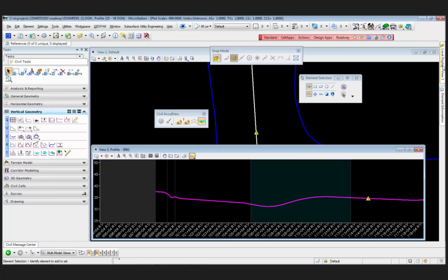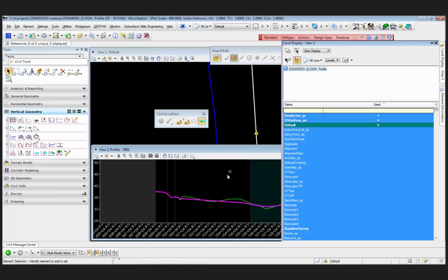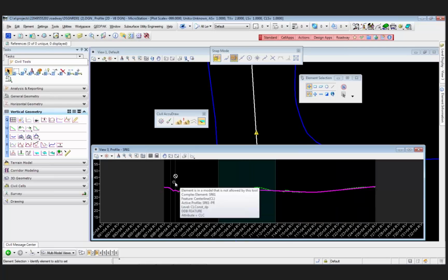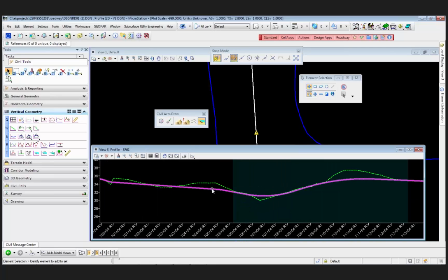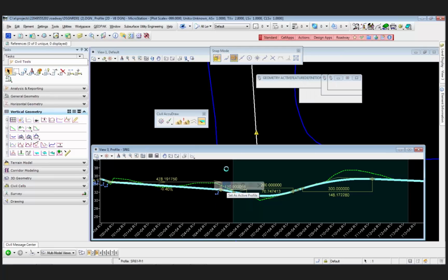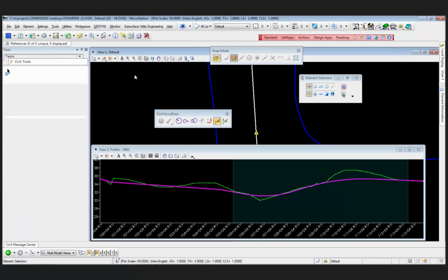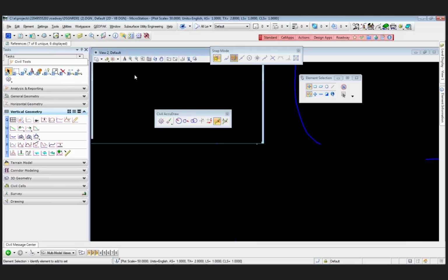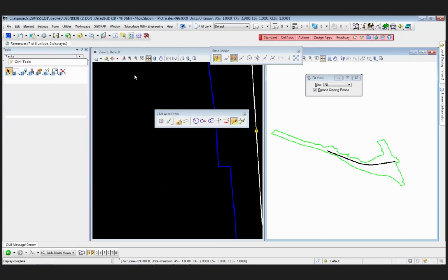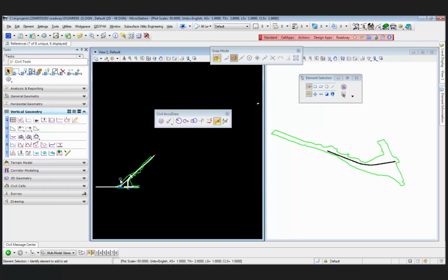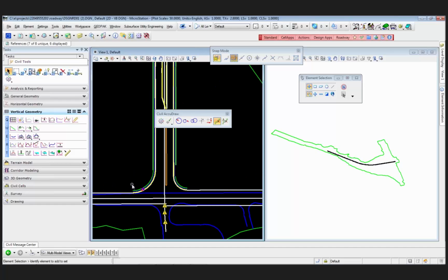And then in order to see the 3D representation of this line, all I'd have to do is click on the line and choose Set as Active Profile. Then if I use my F2 key, it will open up the isometric view, and it will fit the plan view. Let me delete these elements, I don't want those. And it will fit the plan view as well.